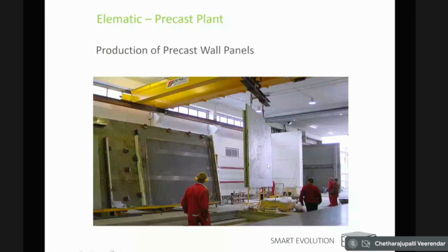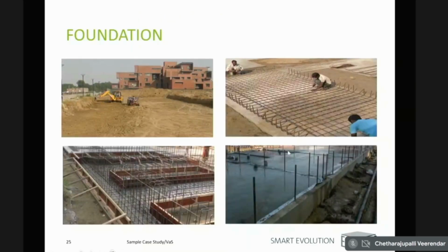So you can see here after production, we are lifting the table out so that extra forces do not apply to the wall. And once it is tilted by about 80 degrees, you pull out the wall from the top using hooks by using an EOT crane. And then it is taken through the wagon to the stockyard and cured also vertically. Walls always get transported also vertically, only produced horizontally.